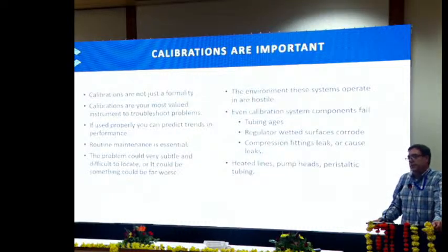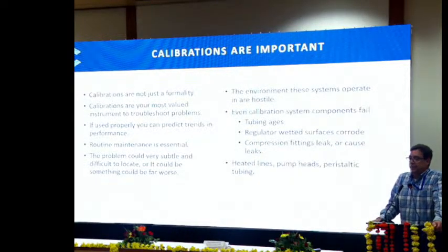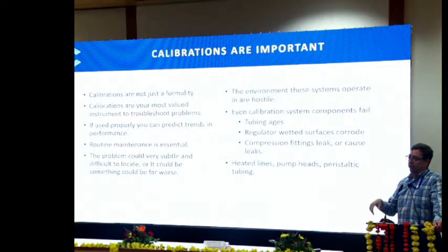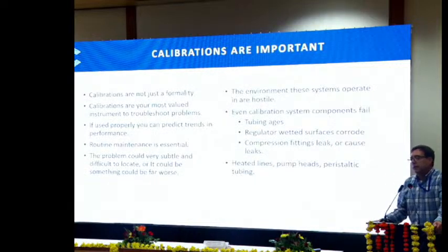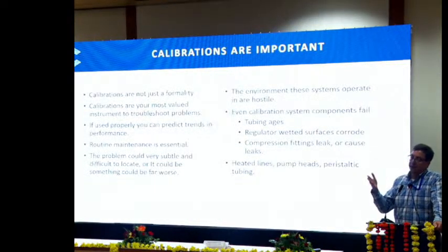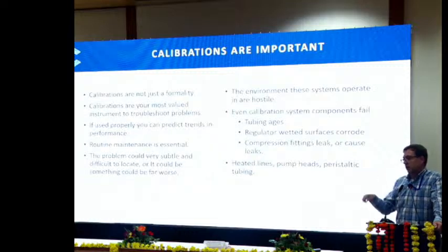Pump heads get leaks. The membranes, the Teflon liner for the head cracks. These things age. Peristaltic tubing, commonly used in your chiller, for example, to help evacuate the water out from the impingers. You need to replace that with some frequency. It gets dry, brittle, it'll fail. And especially where it's being rotated against the rollers on the peristaltic pump, that eventually will crush and cause leaking.